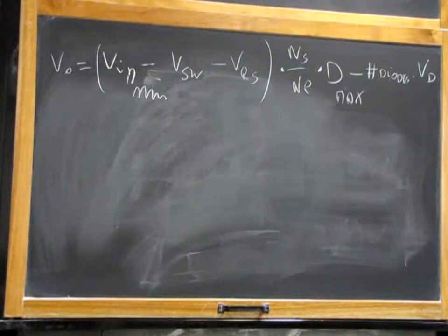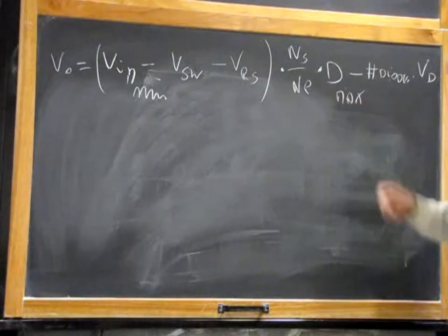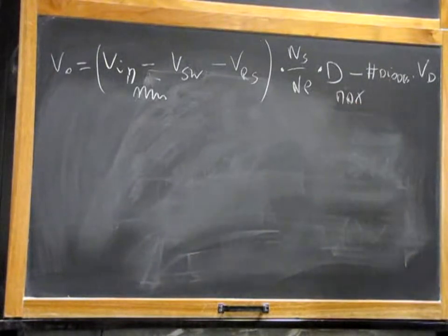I exploit full time my magnetic core, my magnetic component. If D is large, I exploit better the current, the switches, so the current stresses to the switches will be lower. But if my Dmax is too large, well, if my Dmax, for example, is set to be 1.2, well, no, there is something that does not work. You cannot use 1.2 duty cycle. 1.2 in a duty cycle is meaningless.